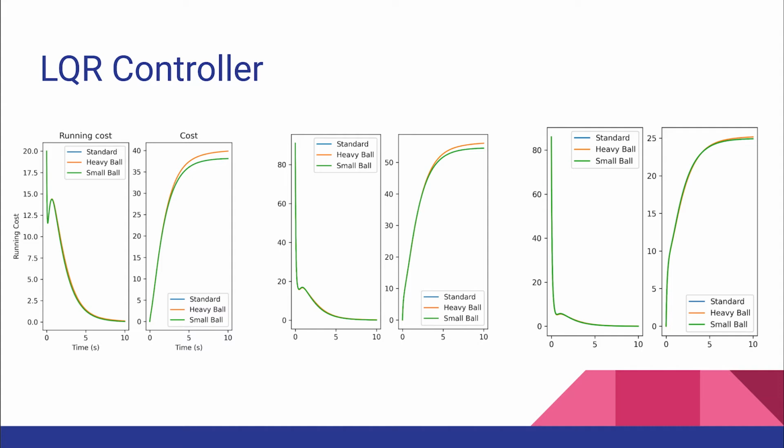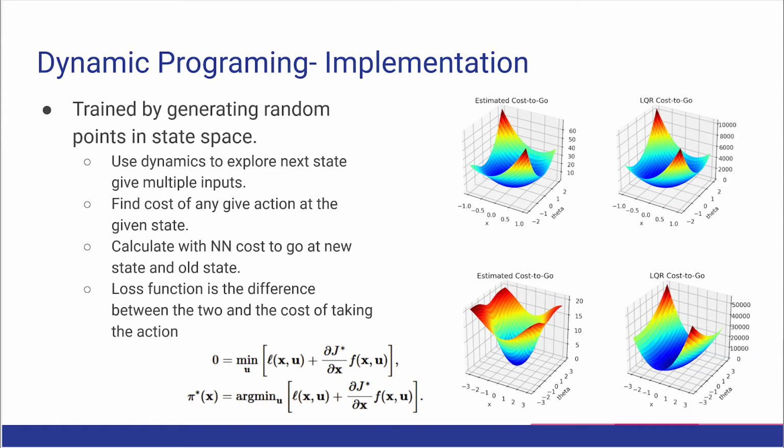We wanted to check the robustness of the LQR controller, so we tried the same controller parameters at 3 different starting points and with 3 slightly different plants, for a total of 9 configurations. To approximate modeling error, we tried a standard ball, a ball that was 20% heavier than expected, and another that was 20% smaller than expected. In all 3 cases, the controller performed spectacularly.